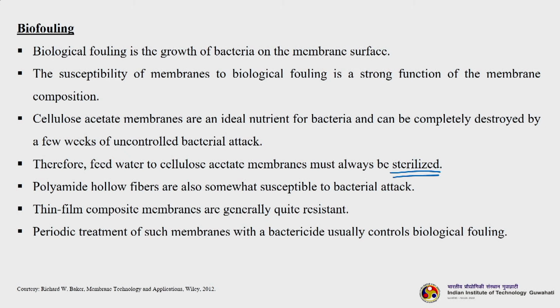At that time we discussed that cellulose acetate or cellulose derivatives are not at all good in terms of biofouling tendencies, because the bacteria which deposit on the surface of the membrane will try to use the cellulose as a substrate for their own growth. Therefore, feed water to cellulose acetate membranes must always be sterilized, but again you are adding extra cost to the entire process.